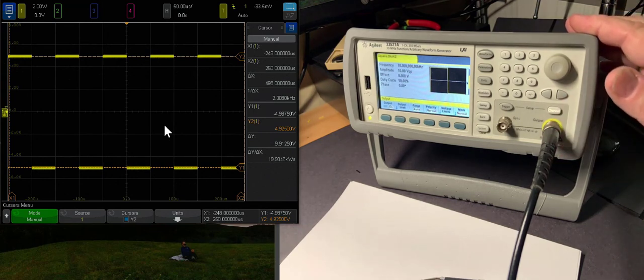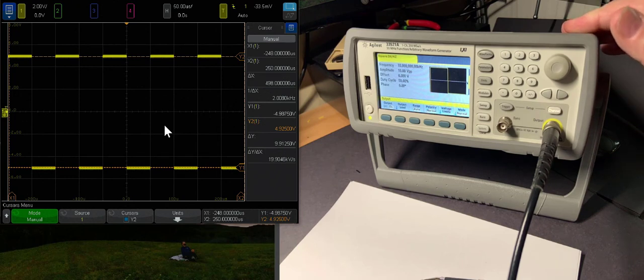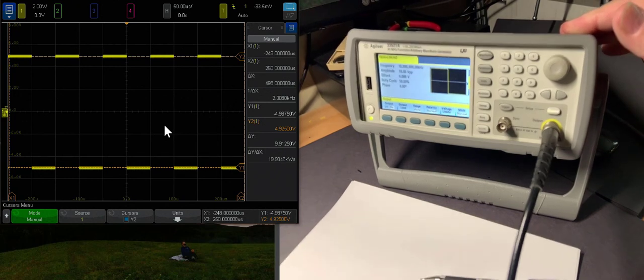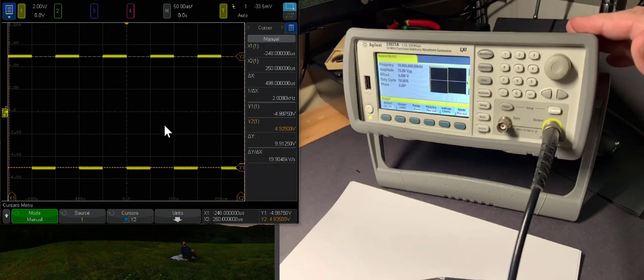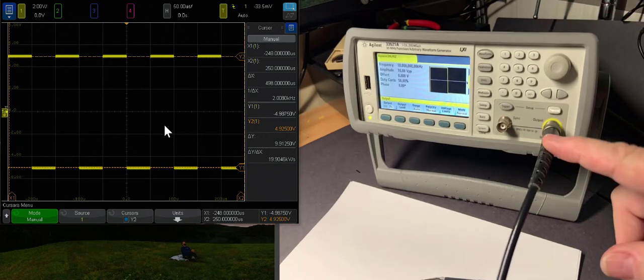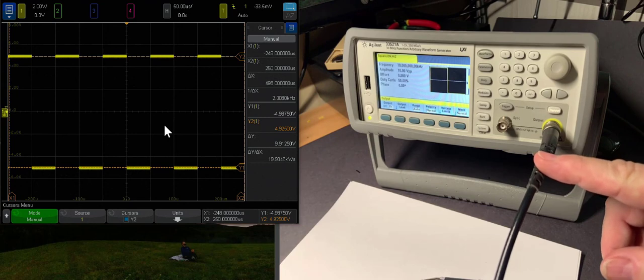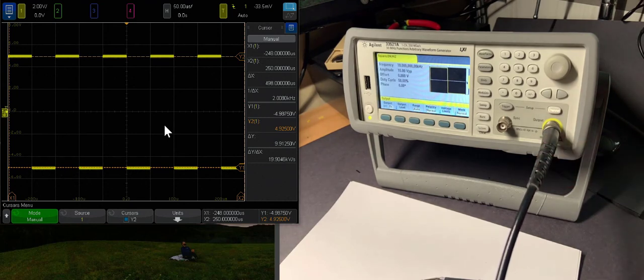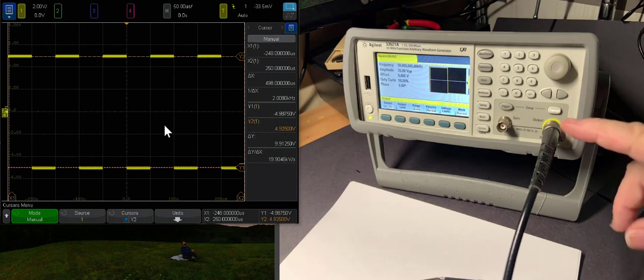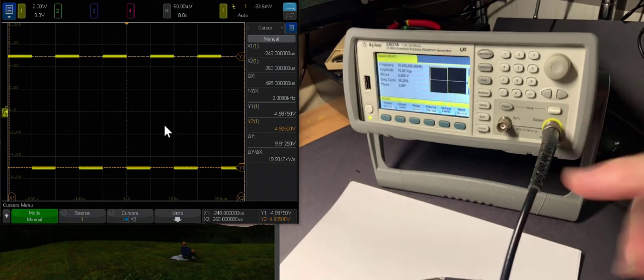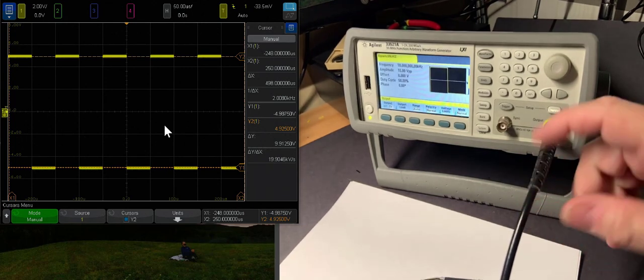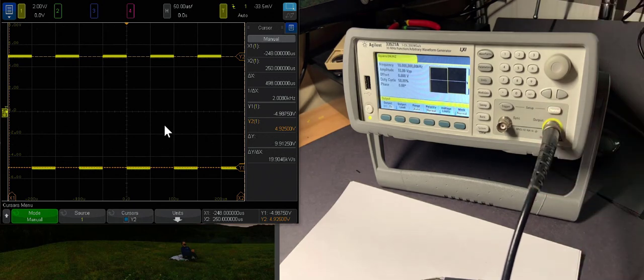And so right now it's set for 4.925 volts. And so we might assume that as an ideal voltage source, no matter what resistive load, no matter what current draw we put on the output of the voltage source, that voltage is going to be constant. It's an ideal voltage source. And to 0th order, that's a pretty good model. And as long as we have a very small load, in other words, a high resistance, so we're not drawing a lot of current, that's a pretty good model.